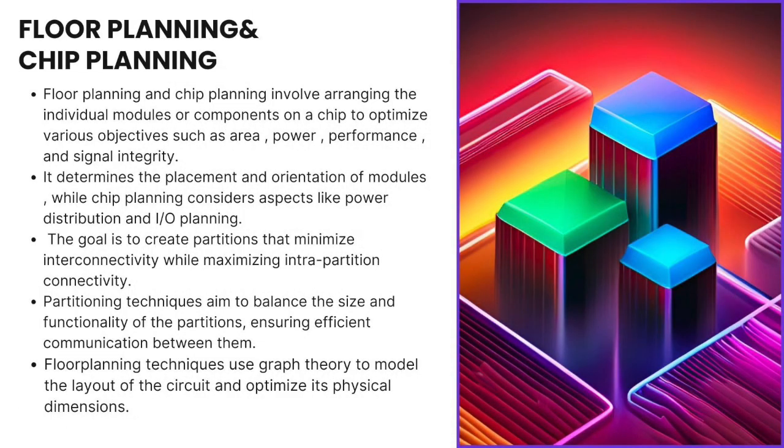Now comes floor planning and chip planning. Floor planning and chip planning involves arranging the individual modules or components on a chip to optimize various objectives such as area, power, performance and signal integrity. In the partitioning section, we made partitions of the given circuit to generate sub-circuits.